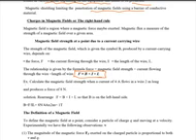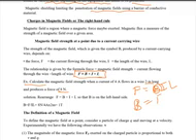For example, calculate the magnetic field strength when a current of 4 ampere flows in a wire 2 meter long, and it produces what? 8 Newton force. As we said, F is equal to what? B times I times what? L. If you are asked for B, B is equivalent to force divided by what? Current times length, I L.